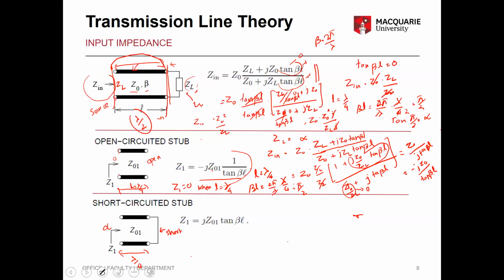For example, if you have a transmission line and you take a length lambda by 4 line from that, then short it and this becomes open. So it doesn't see any effect because of that. If you short it here and this length is lambda by 4, at that particular frequency, this point is open.